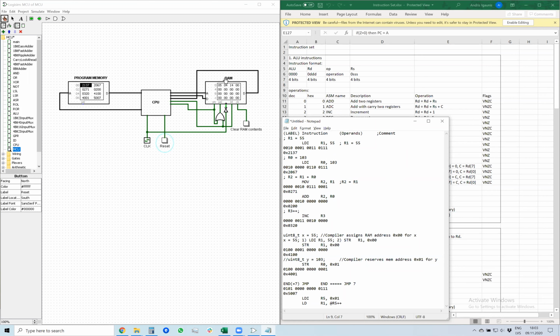Because our processor cannot multiply with the arithmetic logic unit, we don't have such an instruction. So we will need to write software in assembly language which multiplies two numbers. This is actually how some functions for 8-bit microcontrollers are implemented in the C programming language.